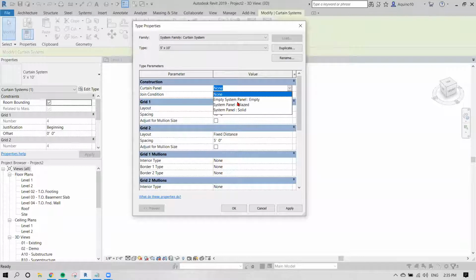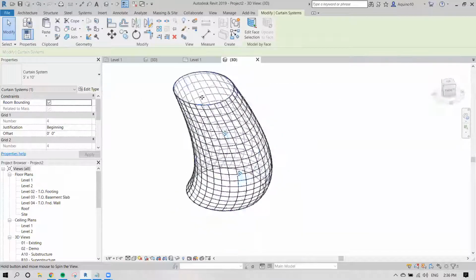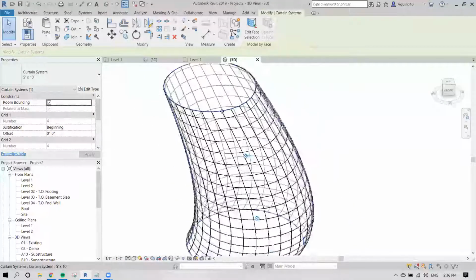So you can't create that basic wall that's 1 inch and represents glass, and so it's curved. You'll have to deal with these straight panel segments. So I would suggest changing the dimensions to something like 2 feet or something smaller, so it appears to be more organic than it is. And these are still straight line segments.